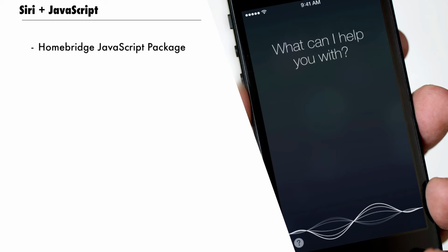So imagine that you have a sensor connected to the Wi-Fi, then Homebridge will get an IP address and a link to it. So you can say IP address/get temperature, and your smart device, the Arduino or the NodeMCU, will respond to that get temperature URL, and with that you basically connected the whole project to iOS and the HomeKit and Siri.